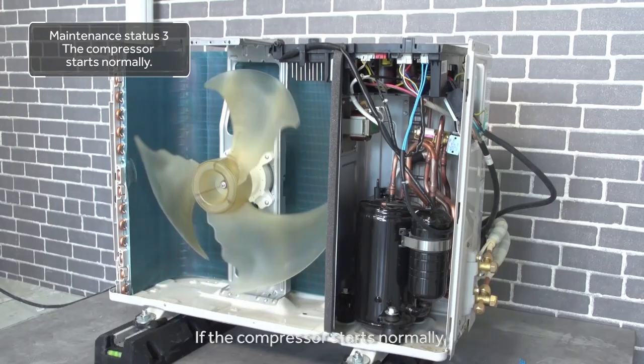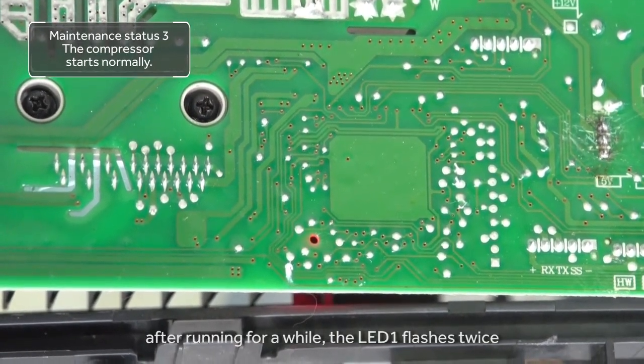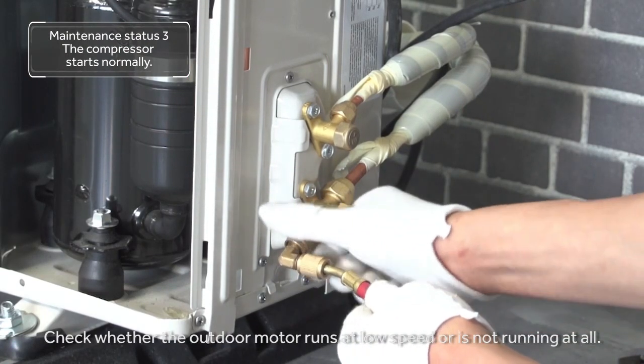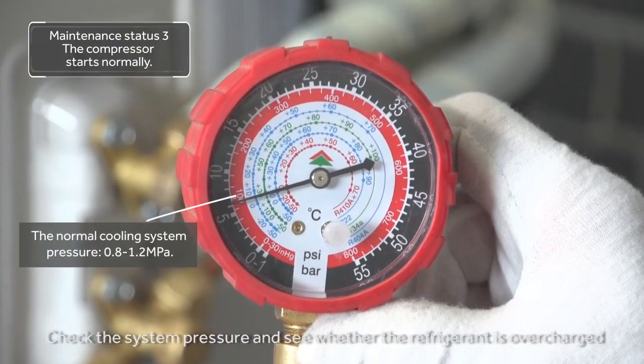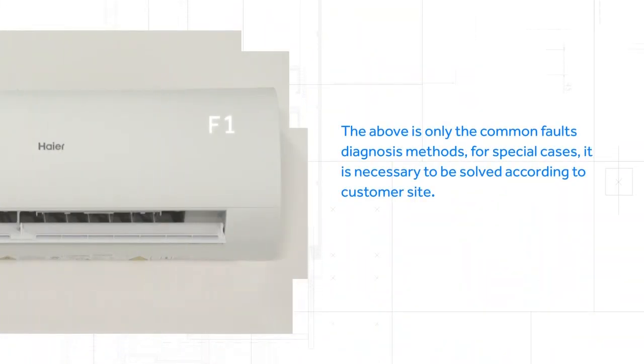If the compressor starts normally and, after running for a while, the LED 1 flashes twice, which indicates overheat protection, check whether the outdoor motor runs at low speed or is not running at all. Check the system pressure and see whether the refrigerant is overcharged. The above are only the common fault diagnosis methods. For special cases, it is necessary to solve them according to the customer site.